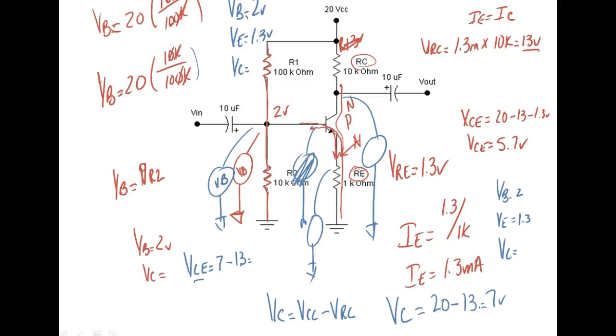So you're up here trying to look at your meter, and you got 2 meter leads out there. What's the odds of one of those flipping? Pretty dang high. You touch 2 of those leads together, you could pop that transistor just like that. And normally we try not to measure on the transistor. We try to measure back here on these resistors.